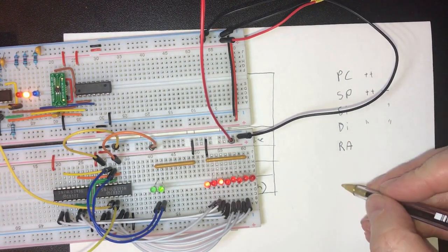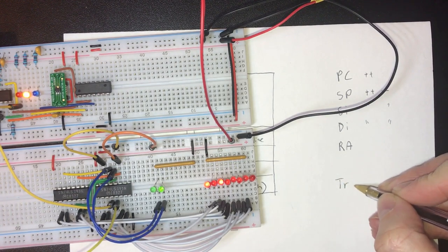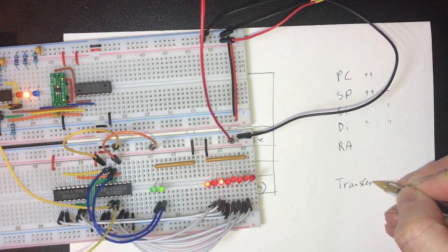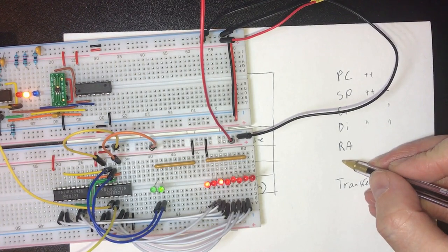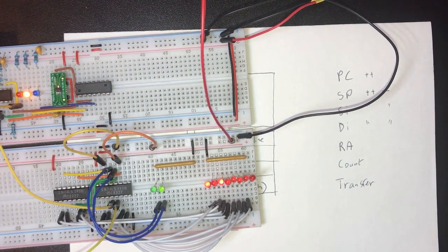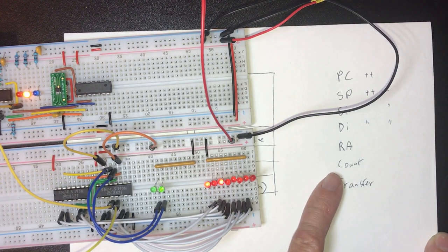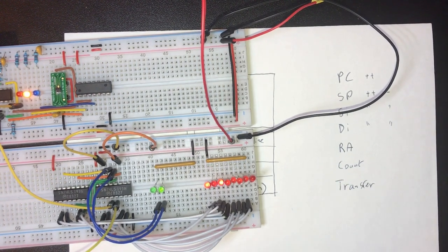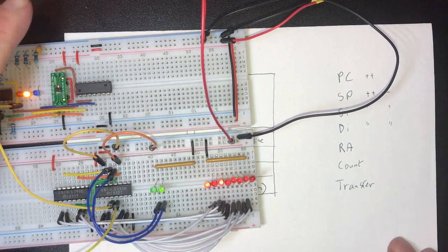So we've got the transfer register, and it might be worth adding a count register, which would not really be used as an address register at all, but having something where we could easily and quickly count to or downwards from a number greater than 255 might be handy. So stick a pin in that, it might be an idea.